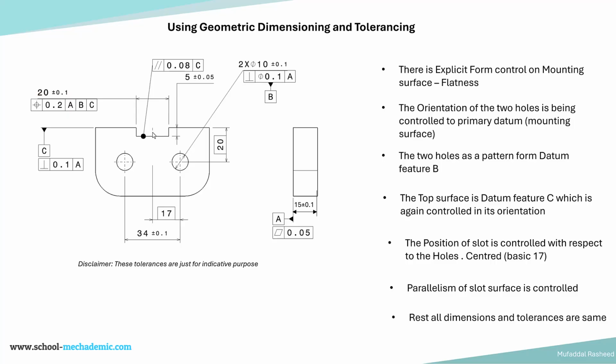And that is basically being controlled with respect to the positions of the two holes. So wherever the holes are positioned, we are not worried about the position of the hole from this point. We are saying that wherever the holes are positioned, the slot should be centered based on those two holes. That's what we are saying through this feature reference frame, this setup.